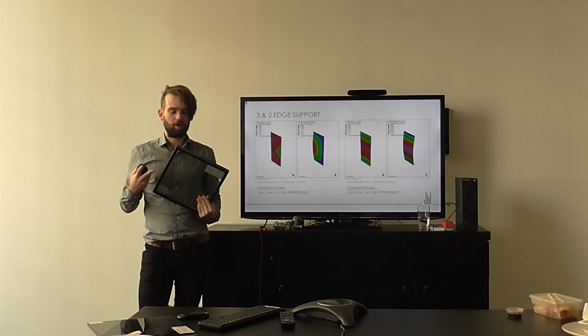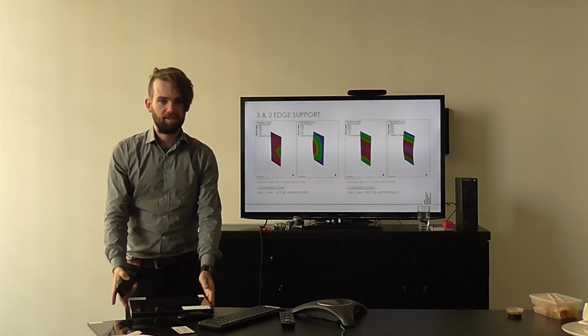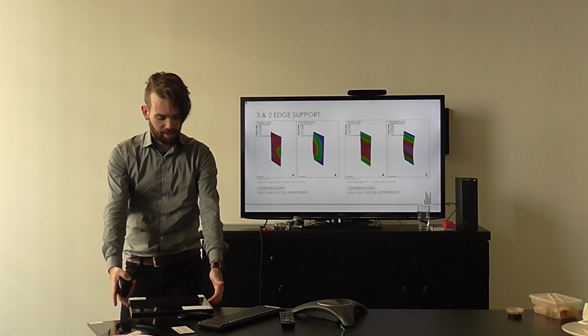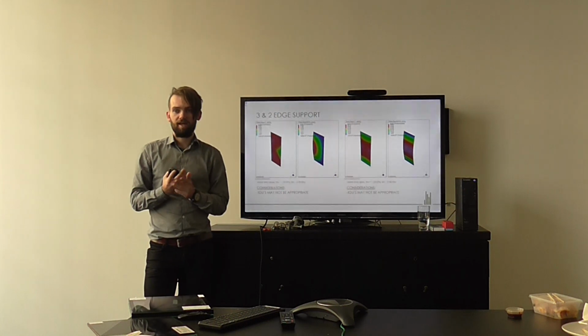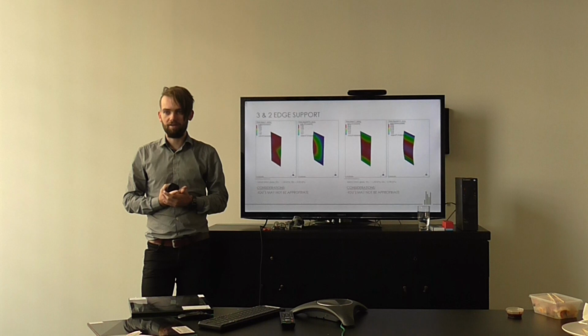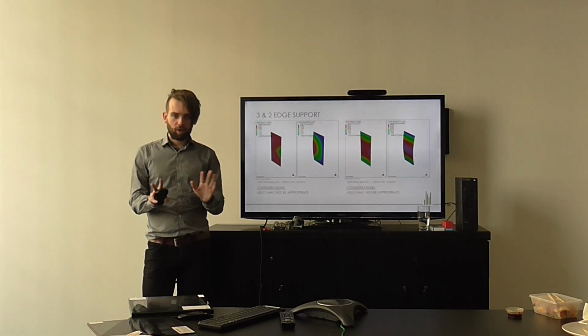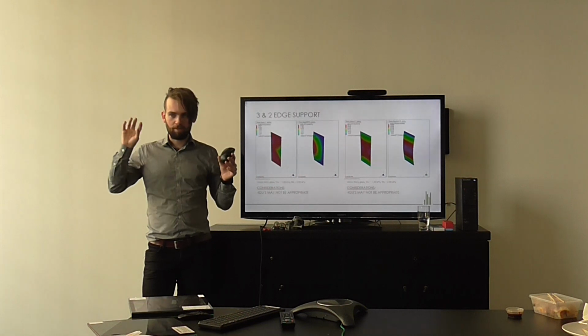I won't get the exact number on it, but essentially if it deflects too much, what can happen is the desiccant and the spacer here can separate from the two pieces of glass, and essentially the IGU is useless. It may start condensating and will need to be replaced. So where possible, if you ever see an unsupported double glazed unit edge, the alarm bell should be going off.